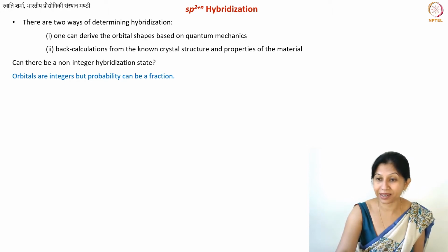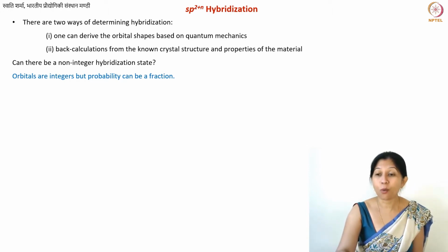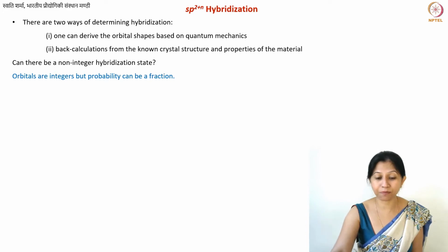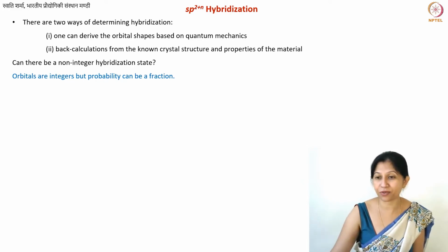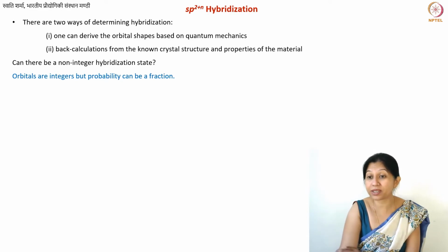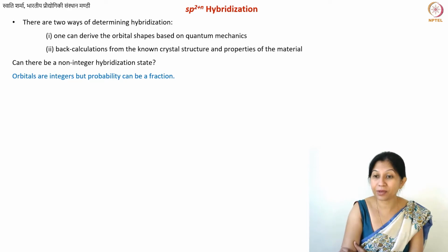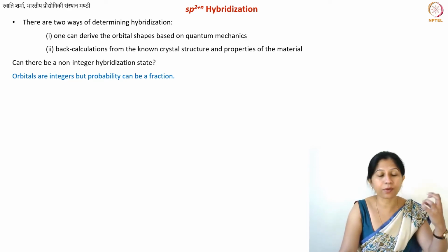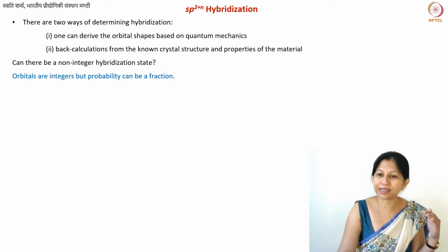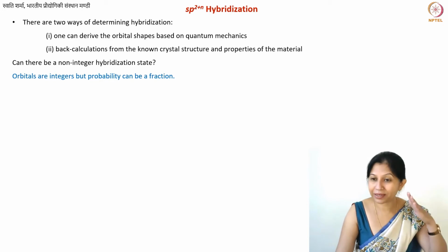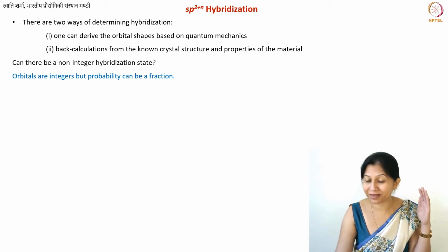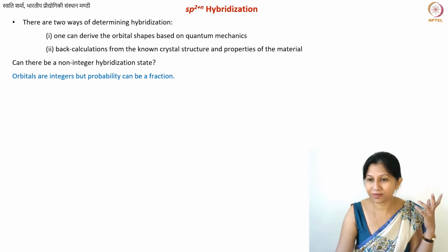You can also calculate the hybridization states, but when we talk about materials in manufacturing aspects, it is easier for us to back calculate the hybridization from the crystal geometries, right? Because the crystal geometries are important for us. And also when we are performing manufacturing on any given material, these crystal geometries can also be observed at a larger scale. So for example, if you are polishing or cutting a diamond, the cutting patterns, the slip planes of diamonds will be according to the crystal structure.